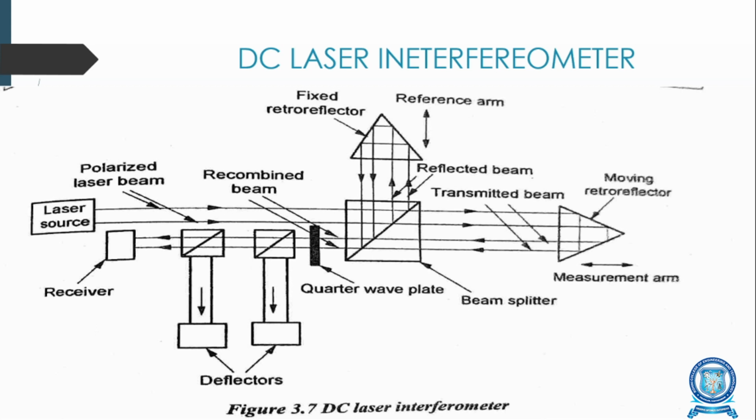The orientation of the plane of this polarized light depends on the phase difference between the light in the two returned beams. The beam after the quarter wave plate is split into three polarization sensitive detectors. As the plane polarized light spins, each detector produces a sinusoidal output waveform.